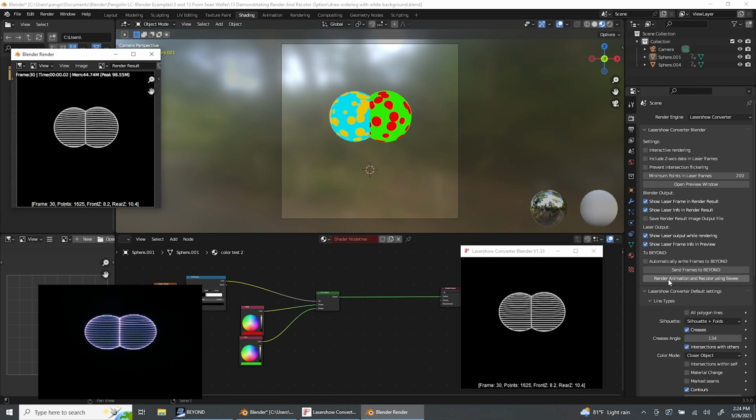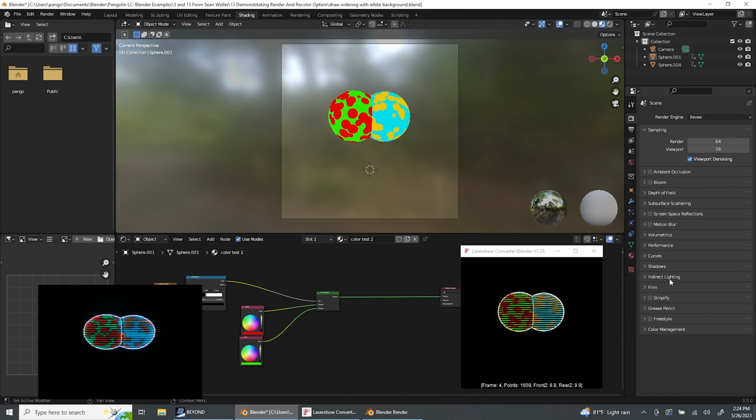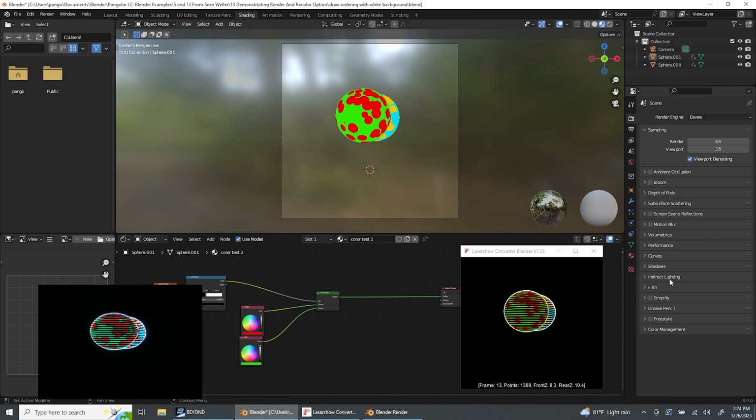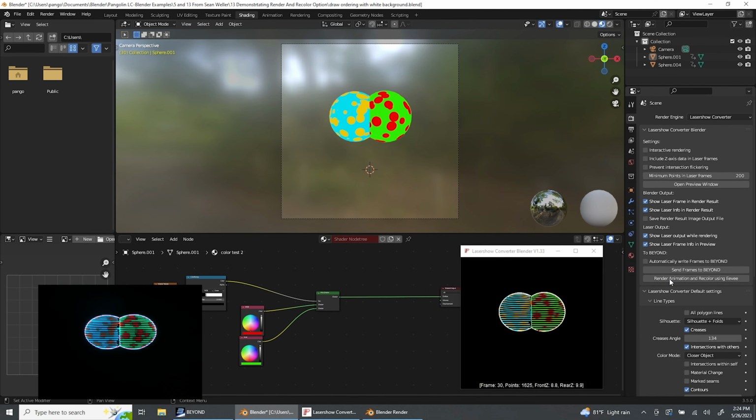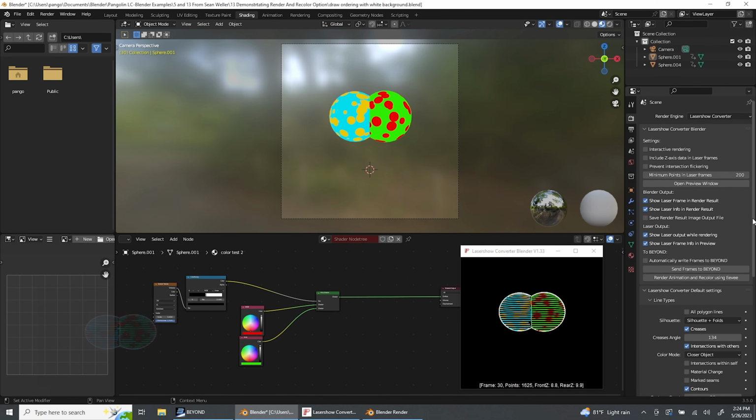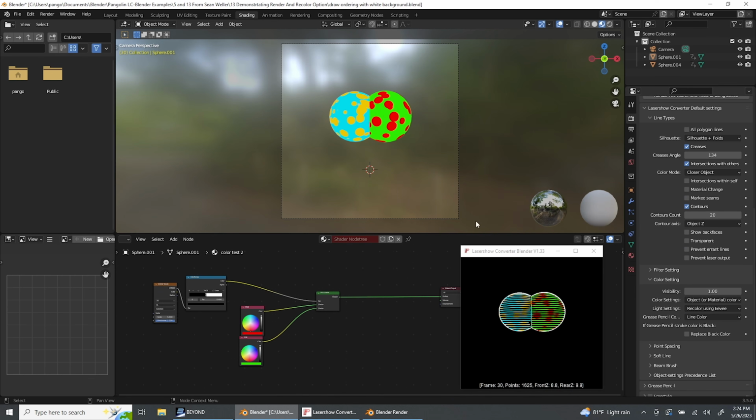But once again, when we try this render animation and recolor using Eevee, what we can do is actually sample the colors here and pick them up. So in order for this to work, what you've got to do is this. For the particular object you want to use this feature on, you have to use this option here called Recolor using Eevee.